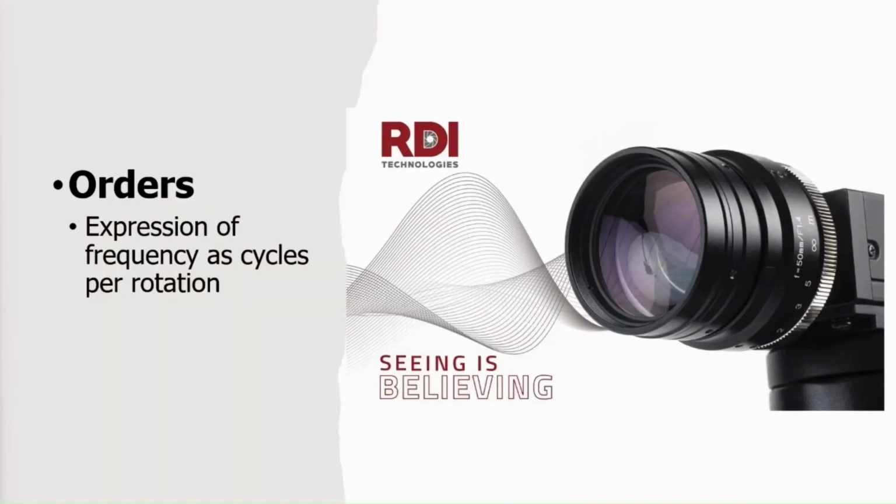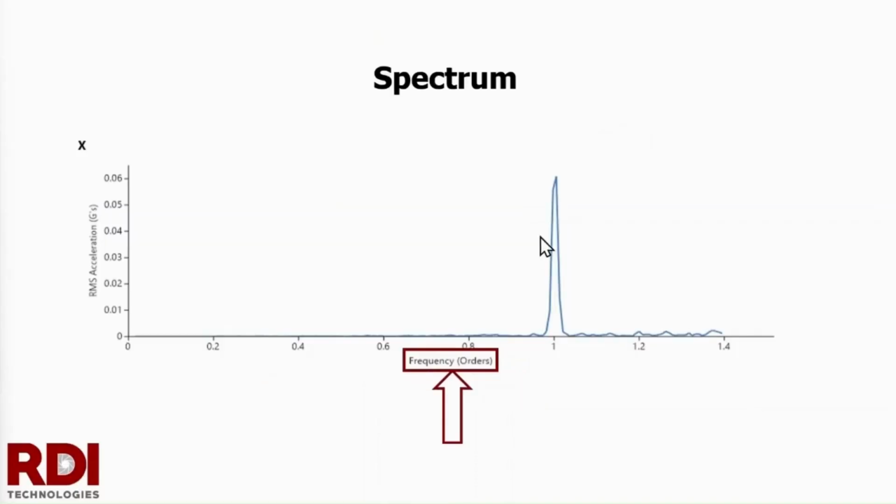And then the third way to express a vibration frequency would be to use orders. Orders is the expression of frequency as cycles per rotation. So with our vibration that occurred at 2600 cycles per minute, if this machine happened to have an RPM of 2600 RPM, then we would say the vibration occurs at one order because the vibration cycles once every time the shaft makes one complete rotation.